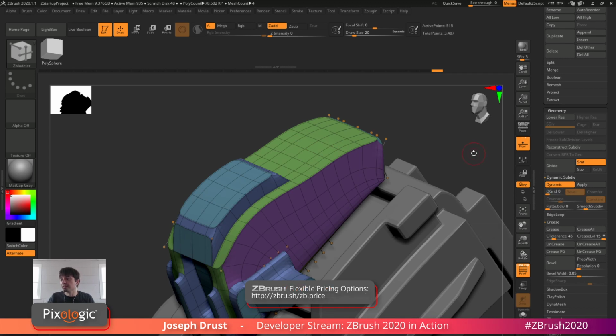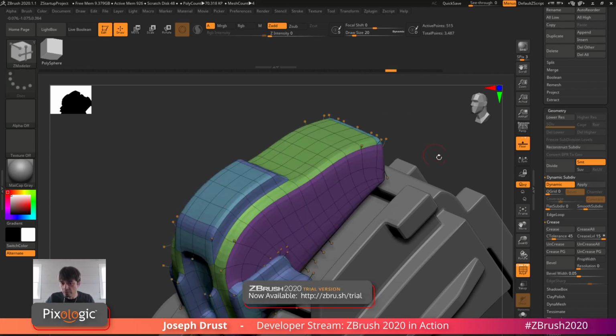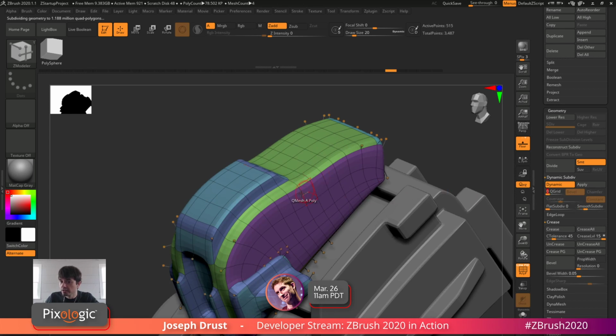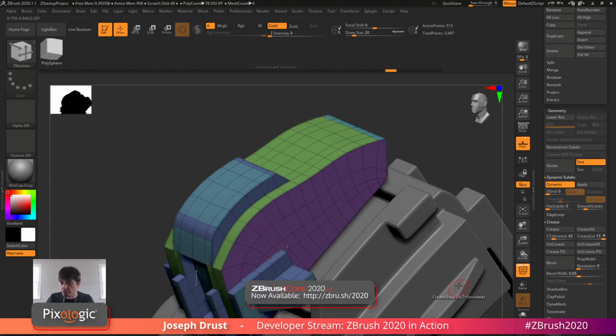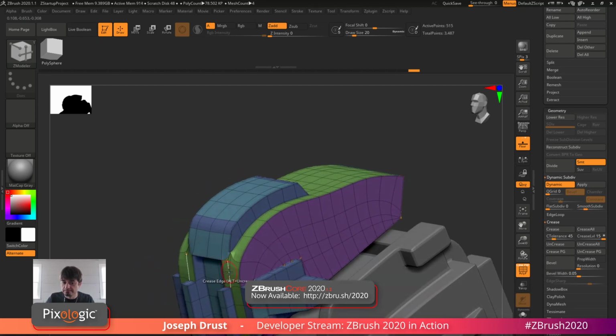The QGrid process is going to add edge bumping, which is basically going to give you that crease visual effect. So that is probably what was mentioned when I was doing this. The QGrid option is going to add basically a crease to every single edge. So that's the difference there. But if you don't have QGrid on, you can control the creasing wherever you want it to be. So if you have anything that's got round surfaces, you probably want to control it manually rather than coming in and using the QGrid option.